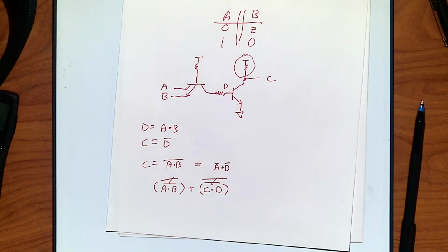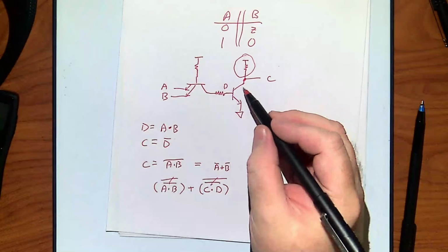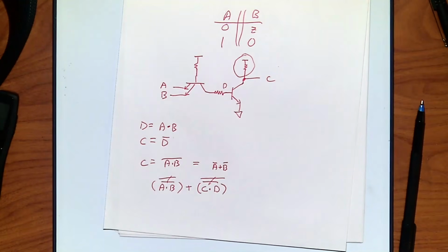Yeah, I either give you zeros or I give you high impedance. So, has anybody ever heard of an open collector output? All right, some have, some haven't. Remember, collector, base, emitter, right? If I don't put that resistor on there, the collector has nothing on it. So when you output, the collector is at Z, which is an open in your circuit. Open collector output means there is no resistor pulling you up. So far, so good? Okay.